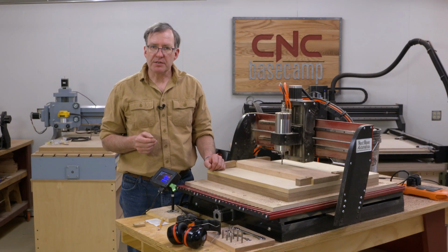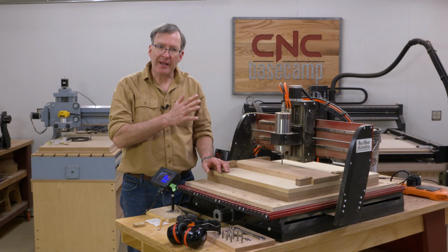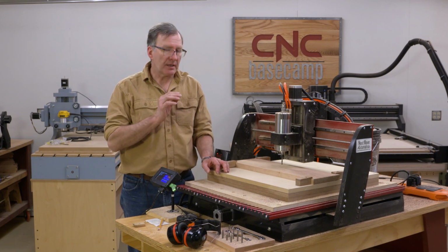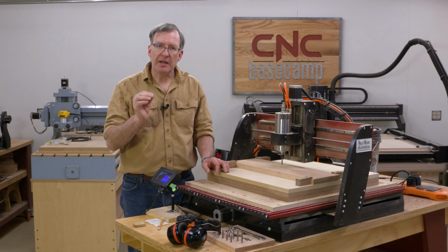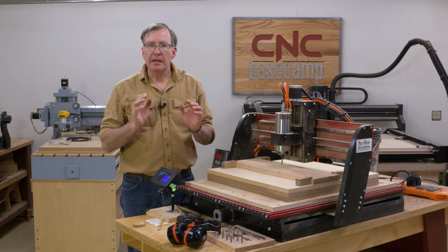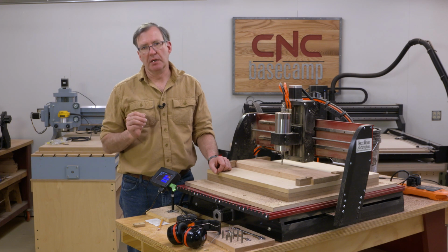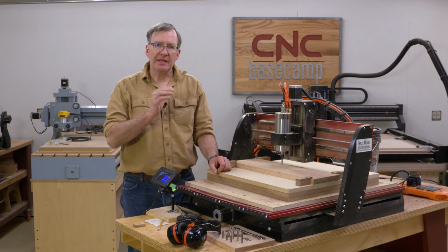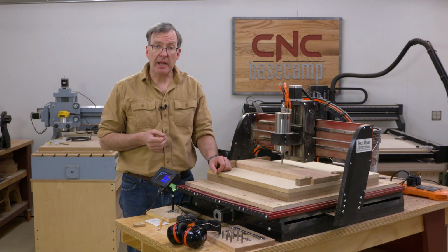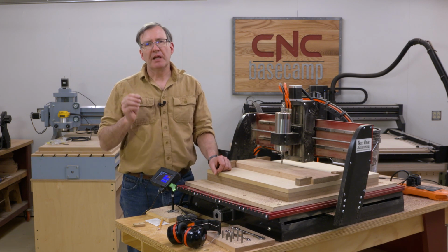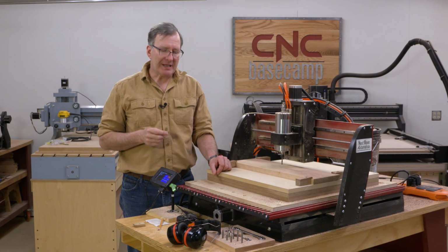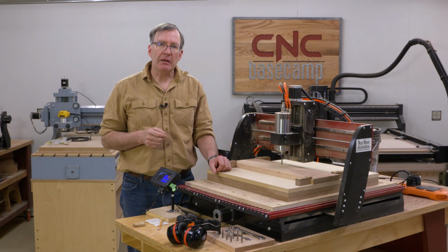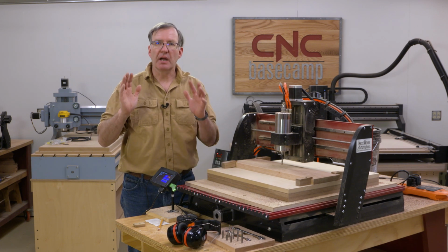Now that we have all the parts cut for our door, the back, and all those exotic wood triangles, it's time to move on to the top and the bottom, the sides and the back of our cabinet. Now the back I'm going to take care of with the table saw because the back is just a piece of 1/4 inch plywood. The sides and the top and bottom I'm going to let the CNC handle. And I'm doing that because there's holes for the shelving pins, which need to be accurate, and I'm using dowels to hold the top, the bottom, and the sides together.